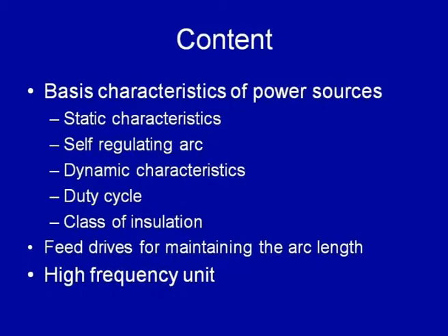Apart from that, we will also see what are the additional devices that we need to use in welding processes, so that the arc can be ignited easily, like high frequency unit, and on what basis we select the proper current for continuous welding or for welding when welding is to be done for a certain period of time. So, that is the part related with the duty cycle.